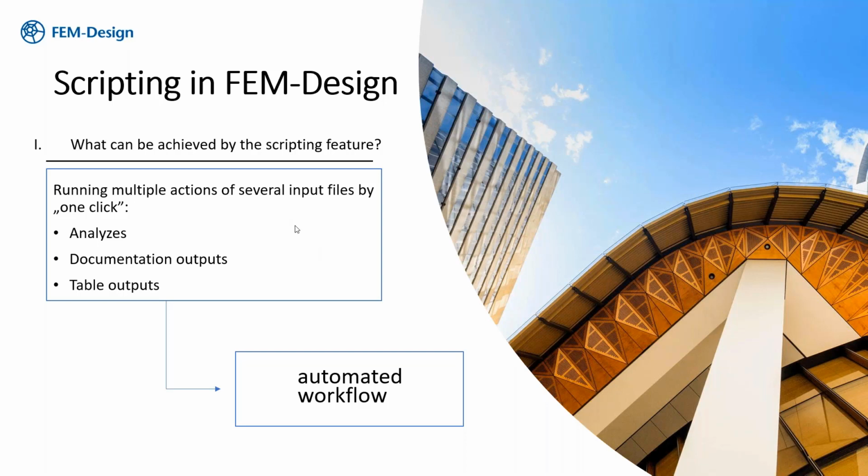For example, in the conceptual phase of the design, when you want to try different configurations of the structure, you can model them, and instead of running one by one and waiting for each simulation, you can write them into the script, and all of them will be run one by one. While they are running, you can do something else, or you can, for example, run them over the night. So actually, it saves your time.